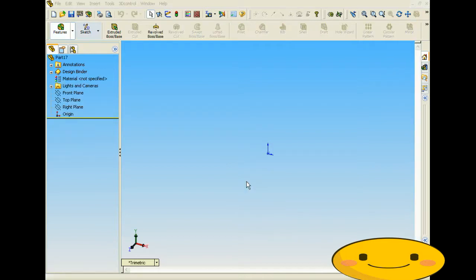This is tutorial number 171, and it covers how to make Boolean bodies within Solidworks. In this tutorial I'm going to show you how to make 2 solid bodies, and from those solid bodies we're going to be creating our Boolean operations. We're going to create the bodies that we'll be using in the next few tutorials to move them into position, then apply the common, add and subtract features to those bodies.